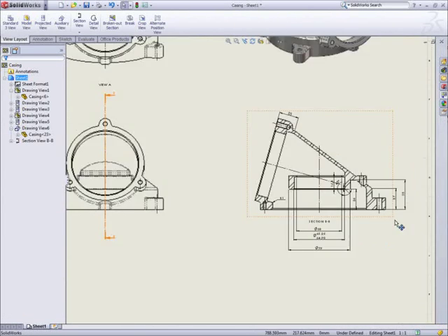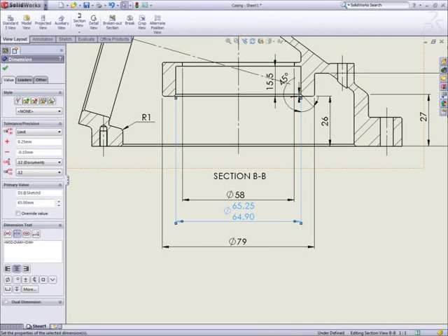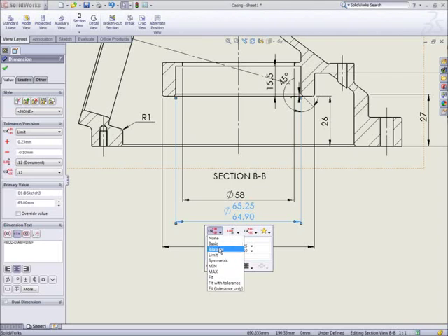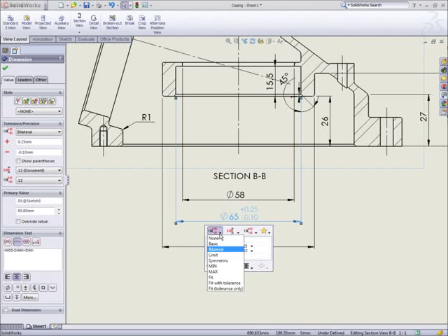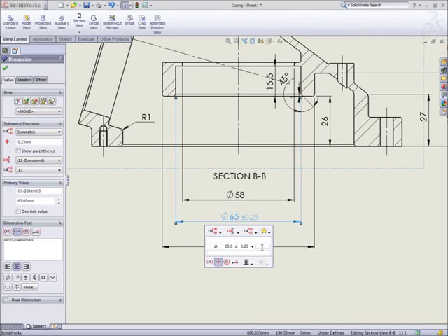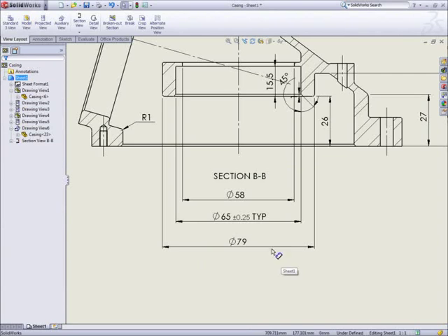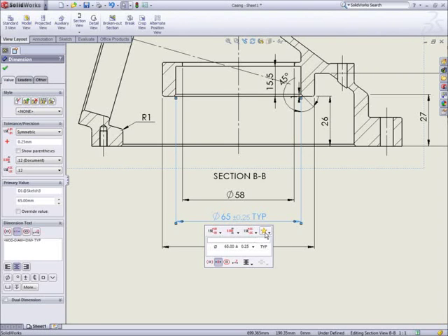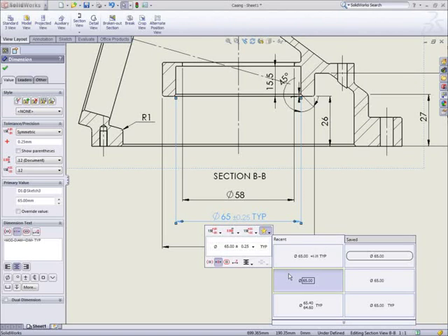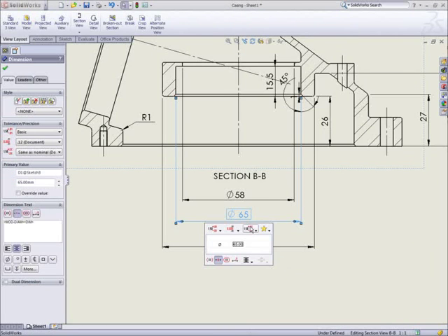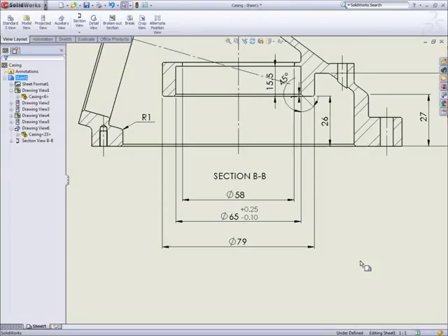Any tolerances, geometric tolerances or surface finish symbols added to the 3D model can be shown on the drawing. A subset of the dimension properties over on the left side of the screen pops up in the dimension palette for quick edits. Tolerance type, sizes and text notes can all be changed here. It also remembers your last few edits so you can recall them instantly and helps you to adhere to predefined company standards. Changes to these tolerances are reflected back in the model, so all design information is always up to date wherever it's used.